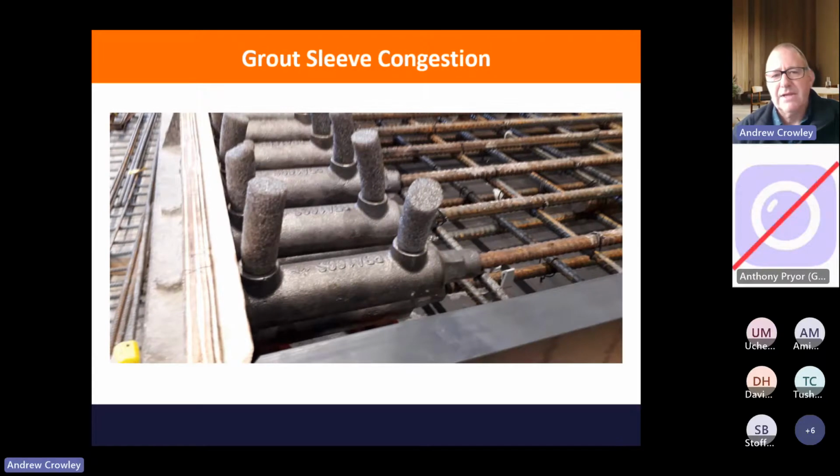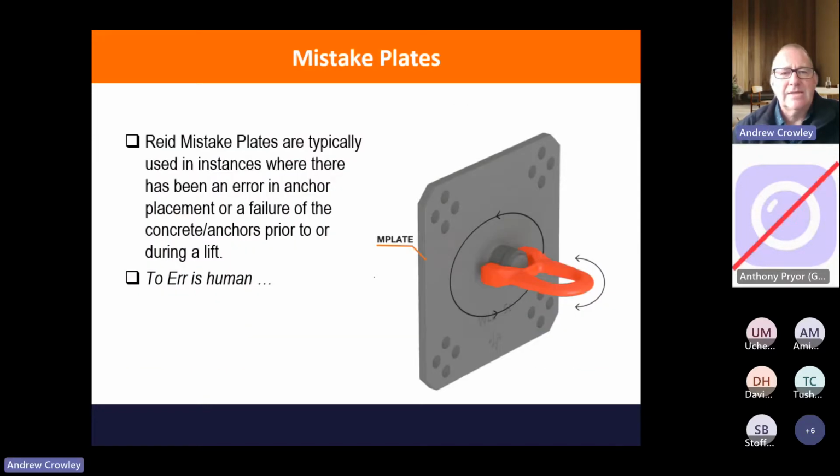And similarly at the other end, you've got grout sleeves, and these are at quite close centers. And again, if you need grout sleeves at these close centers, your walls are too thin. Basically, you need to do something else. And sometimes mistakes are made. Sometimes the lifters don't work, or they can get pulled out or damaged.